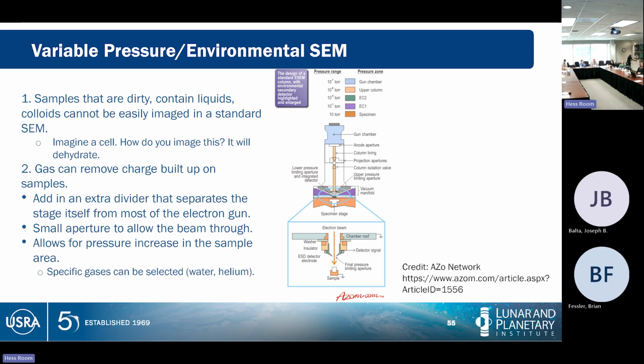Well, what I can do is add a little bit of gas, because instead of the sample itself carrying away the charge, if I have a little bit of gas in the area that was otherwise under vacuum, so at the specimen stage, that gas can help remove charge, and it will help maintain materials that might not be stable under a full vacuum. So if my red blood cell is going to boil under total vacuum, and I let a little bit of gas in there, it can allow the thing to survive better.